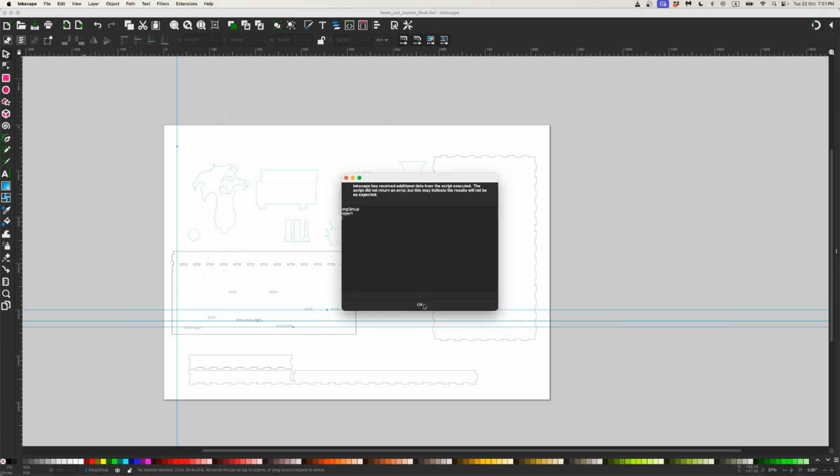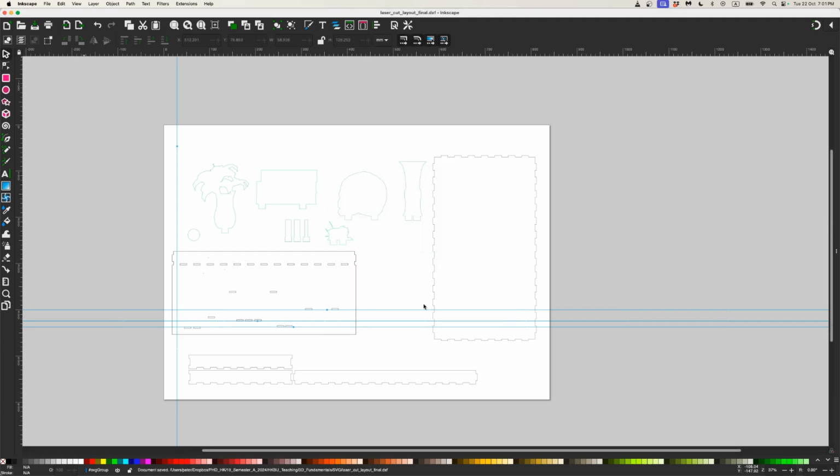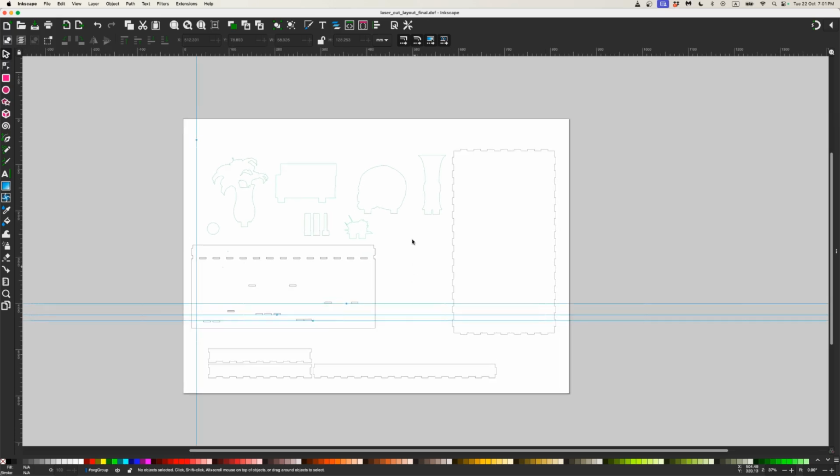And that error, it pops up. Usually it doesn't matter. Sometimes people do have problems getting the DXF to export. I've got some notes in the class document that I'll point you to, and I think usually we can solve these problems. But from my experience, from Inkscape, the DXF R14 works pretty well.